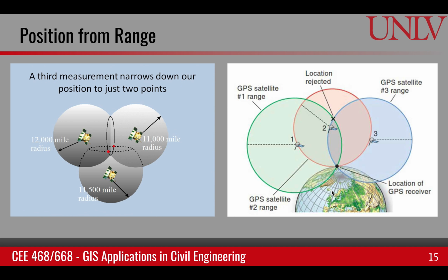Now suppose there was a third satellite that also became available, and now it will be the intersection of the three spheres, which will be 2 points. So the ambiguity in position will be only between these 2 points. So if you had 3 satellites available, you could reject this point because this is not on the Earth and pick this point, and that would be the location.